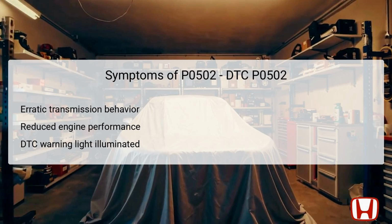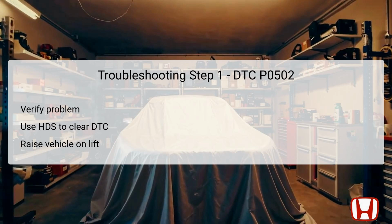It's important to understand that these symptoms can negatively impact both the drivability and safety of the vehicle, necessitating prompt diagnostics and repairs. The first step in troubleshooting DTC P0502 emphasizes the necessity of verifying the problem. Begin by turning the ignition to the on position without starting the engine. Next, clear the DTC using the Honda Diagnostic System, HDS, which is crucial for resetting any existing faults that may have been stored. After clearing the code, securely raise the vehicle on a lift to ensure safe access.